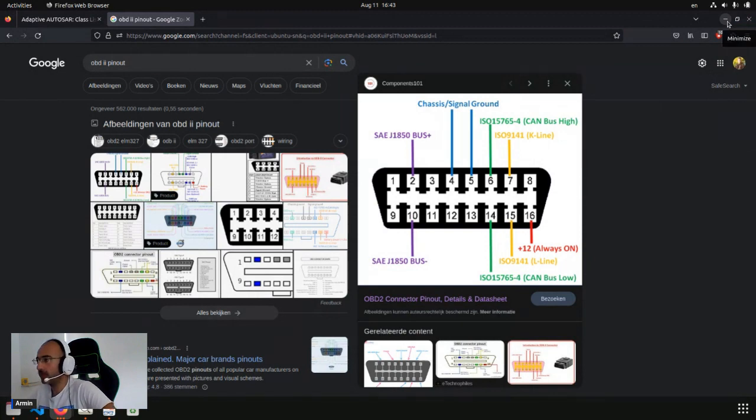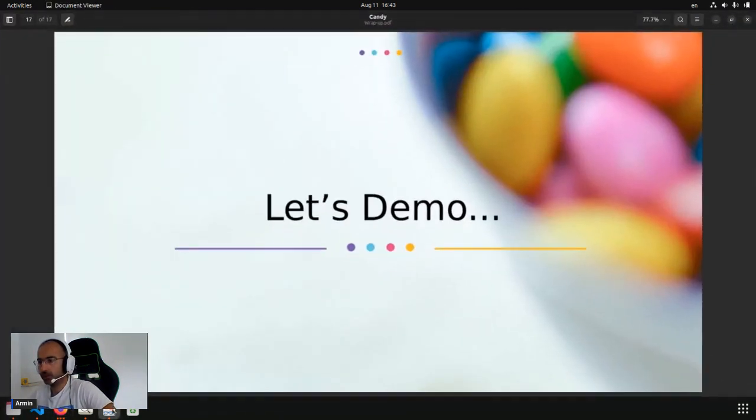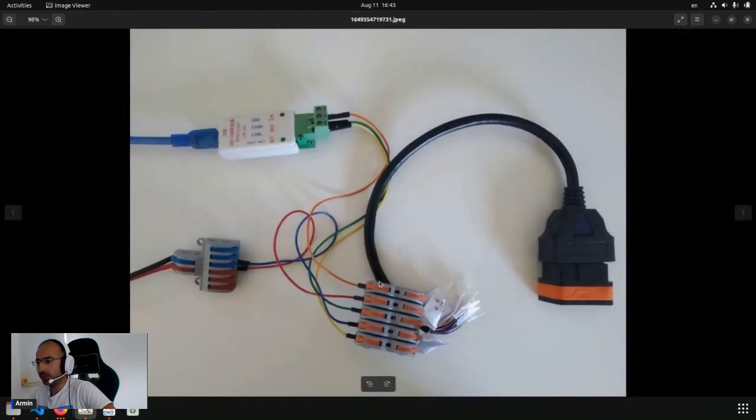So if I return back to the picture, you will see that, okay, there are 5 wires here: 2 grounds, the power, and the CAN high, CAN low, and then I need to somehow interact with this OBD scanner. So I just provide the 12 volt power to the scanner so it can actually run up, and then I mimic the vehicle CAN bus with my USB adapter. So I have the CAN high, CAN low, but it's actually going to finally end up at my system.